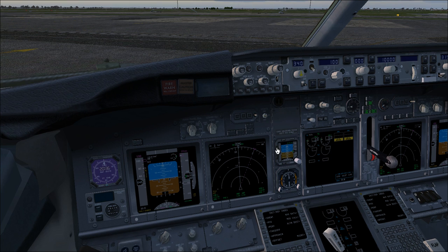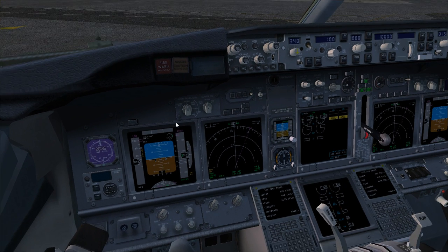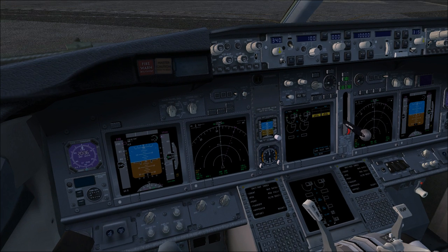If you, for example, select range now, as you can see, the EFIS control also controls the right navigation display, and this is also true for modes or plan switch. Now I get back to normal configuration. I set the source in auto and the control panel in normal, and so I have no more the display source indication.